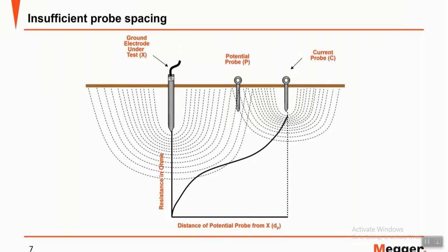If you put the probe at 10%, 20%, 40%, up to 80%, and you get inconsistent results, it means you are in the interference position. So you need to move the current probe far away from the beginning position, and you can try again with the same procedure.